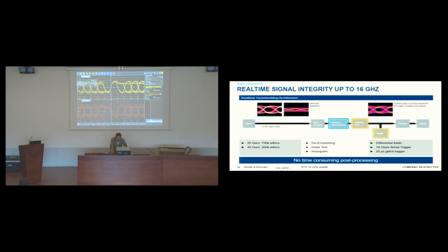I'm clicking over this icon here. I can get a schematic of how the signal flow is going through the hardware. And in this tab here we have differential signals, the differential block. So we can calculate in real time here differential and common mode signals of every combination of our oscilloscope.